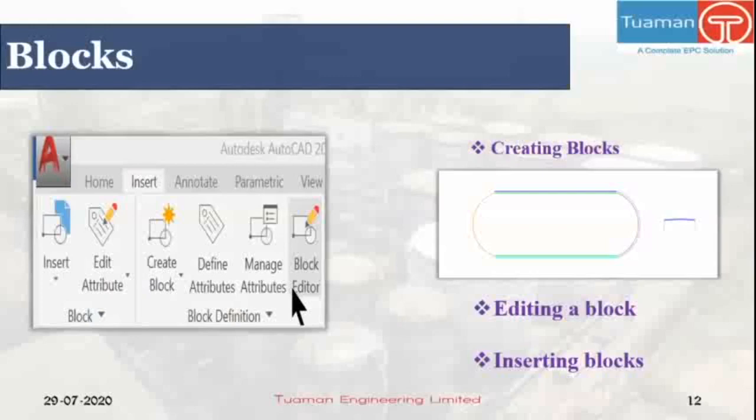When a new drawing is created, it does not contain any block definition unless blocks were stored in the drawing template. So you either have to create new blocks or insert blocks from other drawings. When a drawing file is inserted into another drawing, all block definitions of the inserted file will be added to a new drawing.